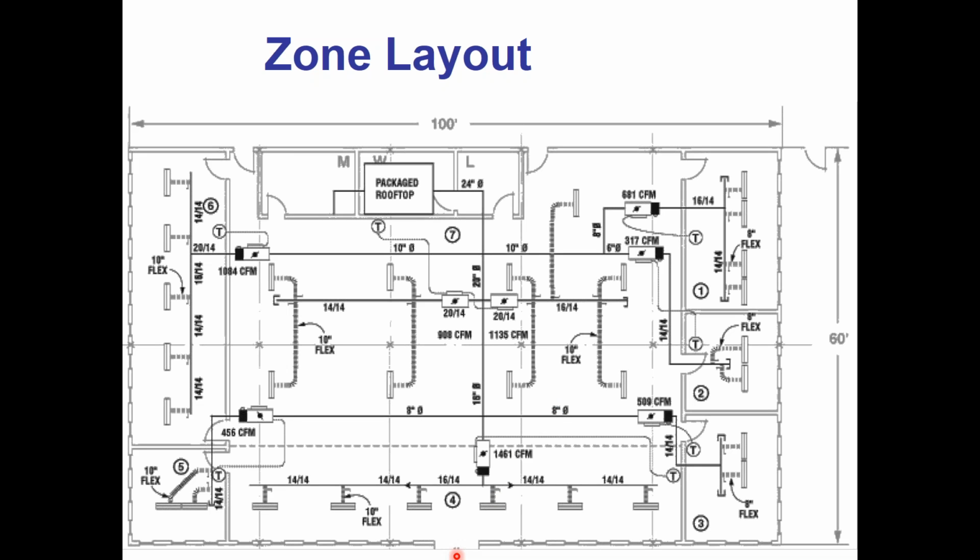That's also one of the reasons why we can't have the air handler provide my heating for me. It does a little bit of morning warm-up, but then remember, it's done for the day, and it's cooling only the rest of the day.